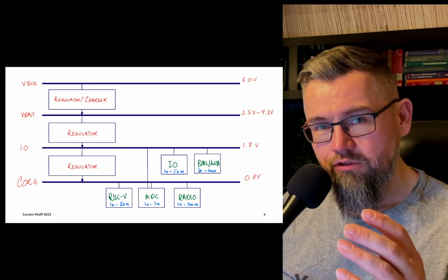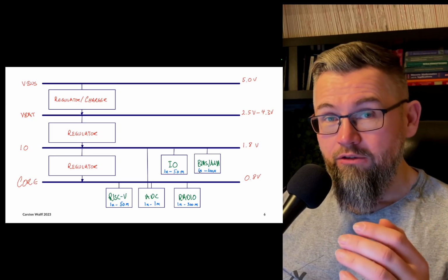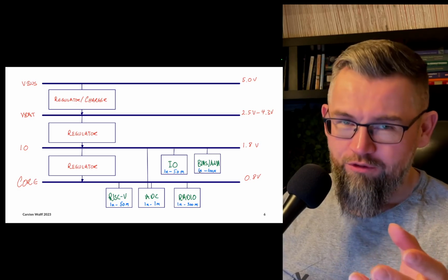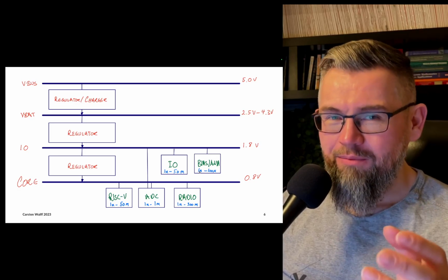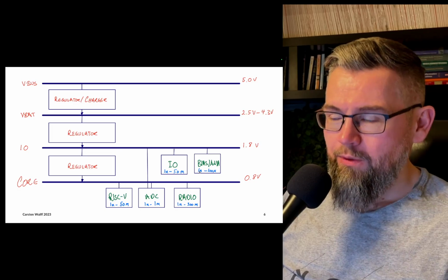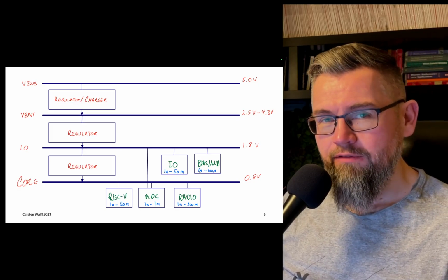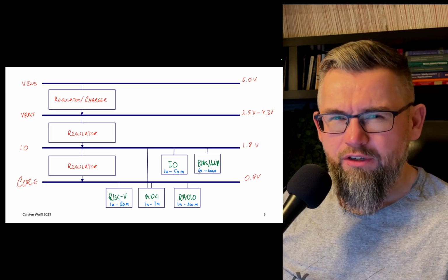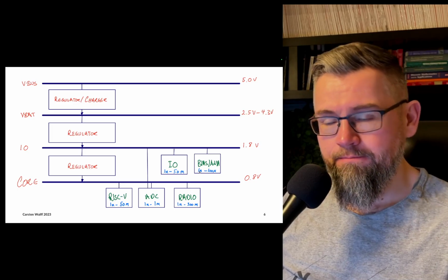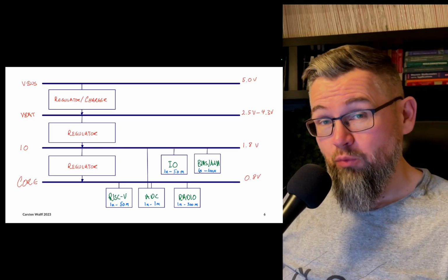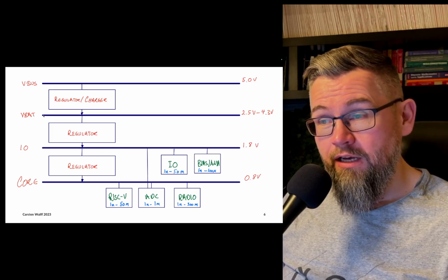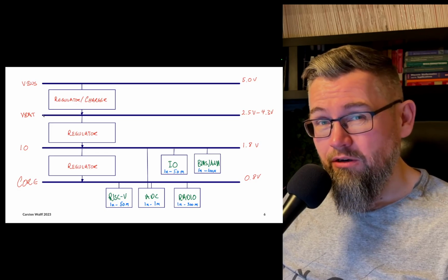Now, if you change the voltage too much, well, then your timing becomes quite variable. Of course, your threshold voltage will also change quite a bit, so maybe the voltage of VDD is not a big impact, but it's going to have an impact. Anyway, let's assume you actually need something relatively precise. Relatively precise is plus minus 5%. Pretty okay is plus minus 10. Quite insane is plus minus 1. And plus minus 1% is what you need when you want to charge a battery towards the end of the cycle. And that's quite hard.